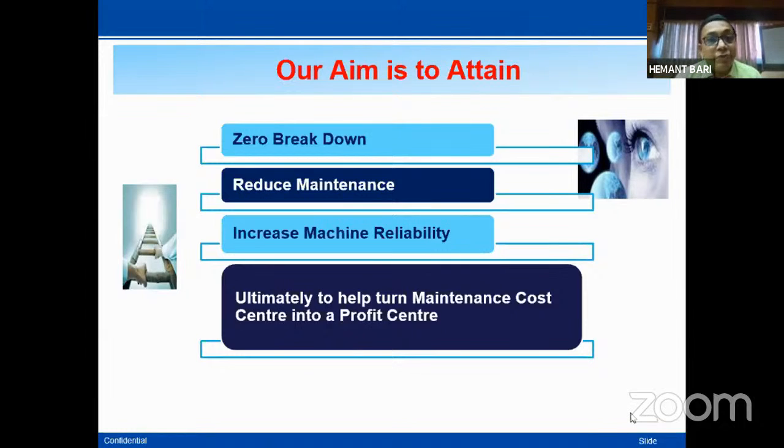Suppose some machine is running at 4.5 millimeter per second vibration and the limit is 7.1, and you measure the vibration 6.5. 4.5 से 6.5 हो गया means some kind of deviation has occurred. Due to what reason? I will say alignment disturb. आपने उसी टाइम पे अलाइनमेंट कर लिया तो आपका कपलिंग का बुश बच जाएगा, बेयरिंग के ऊपर एक्सेस लोडिंग नहीं आएगा, एंड इट विल टेक योर मेंटेनेंस टाइम 6 आवर्स और 5,000 रुपए मैन एंड मटेरियल कॉस्ट आ गया.